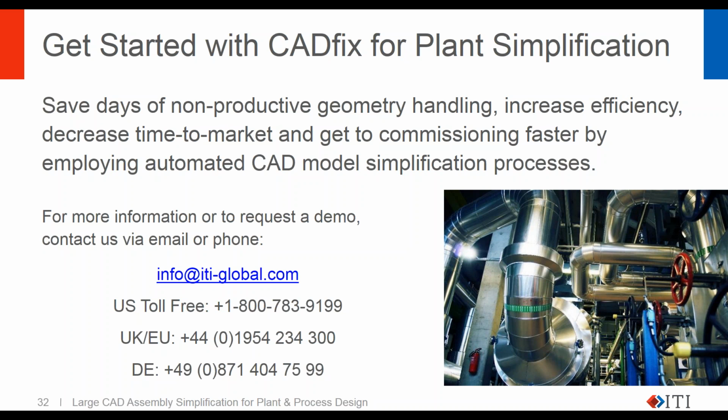Great. If someone selects NX as an input format, is it possible that the resulting simplified geometry will be in NX native format? No, we do not have an NX native export at the moment. What we would do for NX is we would export to JT or to Parasolid.